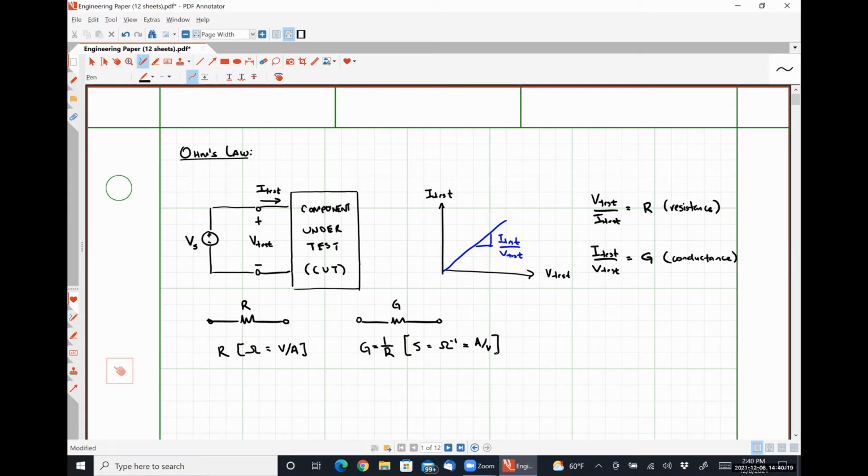Anybody hook up something and apply 5 volts directly to the diode? If you guys didn't do that, then you paid much better attention to the instructions than any of my freshman classes ever did, okay? The purpose of the resistor there was to limit the amount of current that flowed through the LED so that it didn't burn out, okay?